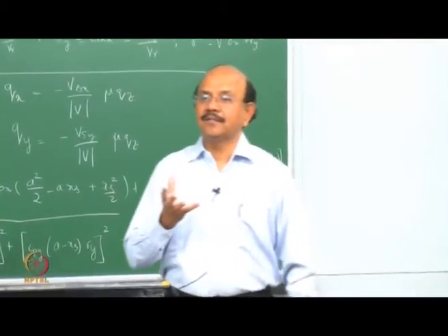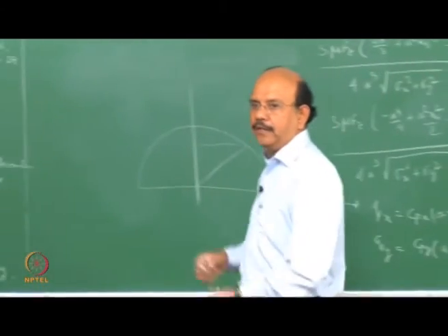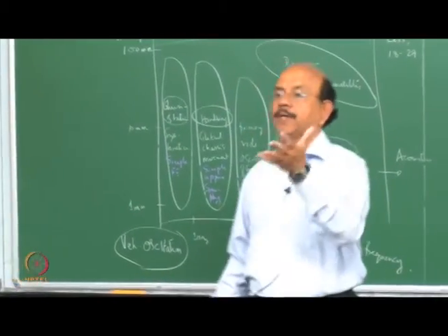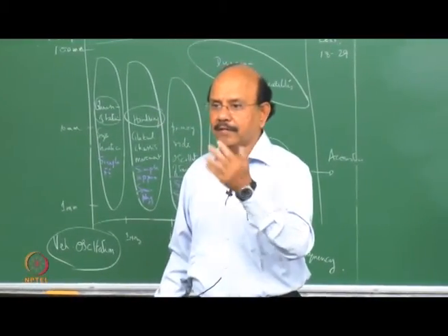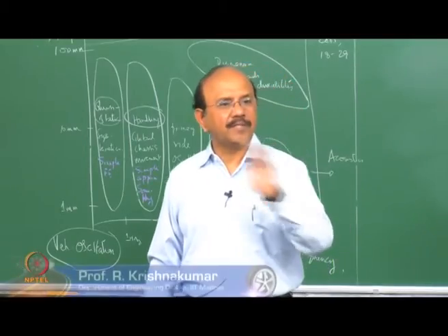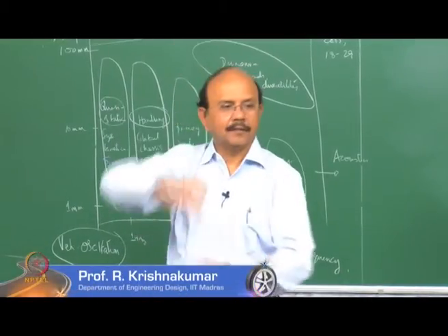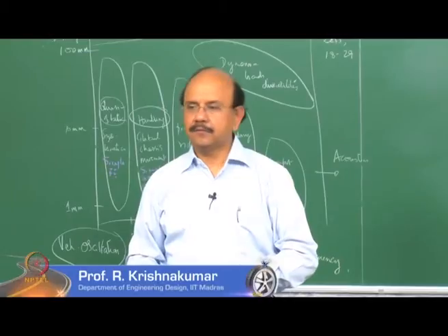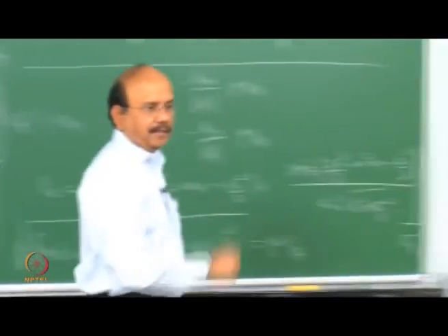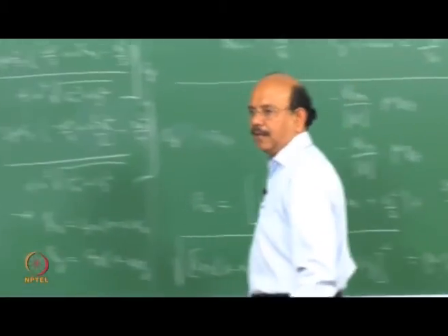So in other words, whatever friction the longitudinal force was holding now gets transmitted to the lateral force. So lateral force becomes high. Lateral force should be just enough to compensate for my centripetal acceleration. But lateral force becomes high, and the whole vehicle overturns. We'll explain that in the next class before we go to the lateral dynamics.